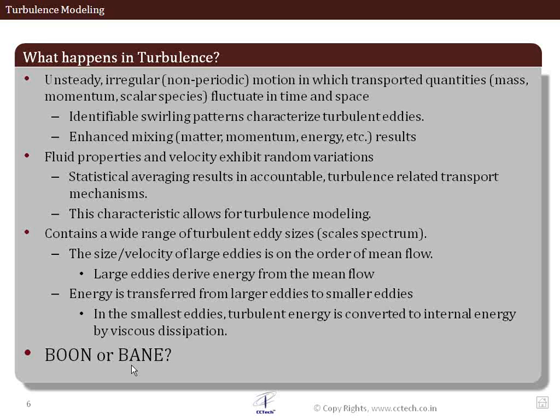So what happens in turbulence is, you can imagine, a particle enters into the domain. It doesn't just go straight out of the domain, but it spends a lot of time mixing together, interacting with the walls, spending its time together, and it needs energy for this. And the energy that the fluid particle gets is from the pressure which is applied at the inlet, and the difference in pressure, that is a pressure drop, which is driving the flow. And this pressure drop is eaten up by the fluid particle in spending more time than required inside the domain. So the residence time does increase, it does increase the amount of mixing inside the flow domain, but the cost we have to pay is the loss in pressure.